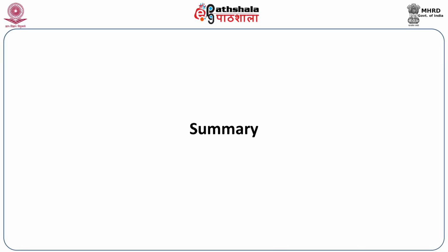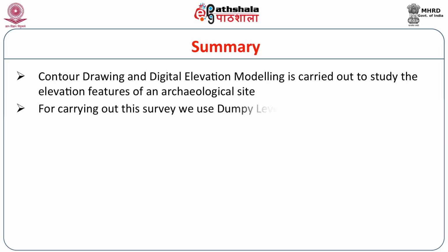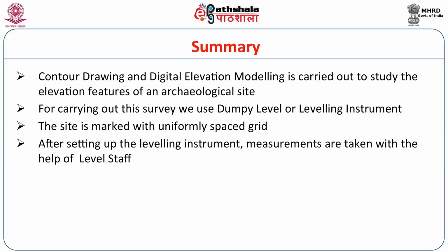To sum up what we have learnt today, the contour drawing and digital elevation modeling is carried out to study the elevation features of an archaeological site. For carrying out this survey, we use a dumpy level or leveling instrument. The site is marked with a uniformly spaced grid, and then after setting up the leveling instrument, measurements are taken with the help of a leveling staff.